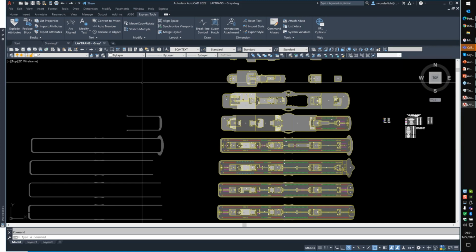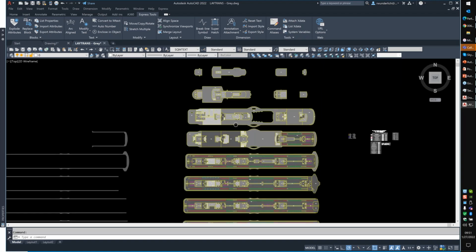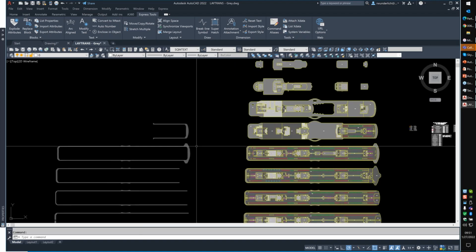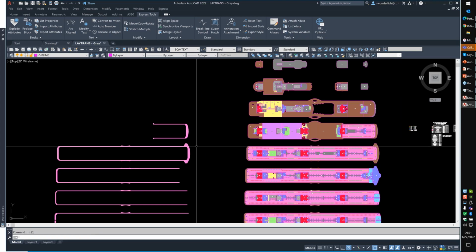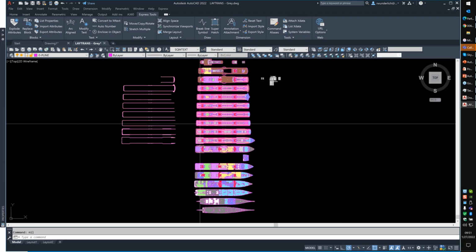So going back to the PDF that I talked about with that square meter standards, right? You can tell that this has none of the correct colors. So with some quick Lisp routines and some things that I've done, I can type in DSQM. Now it's my design colors. I can type TSQM. That will update all of my gray stuff to be correct. And then this is where I can do some of the other things.